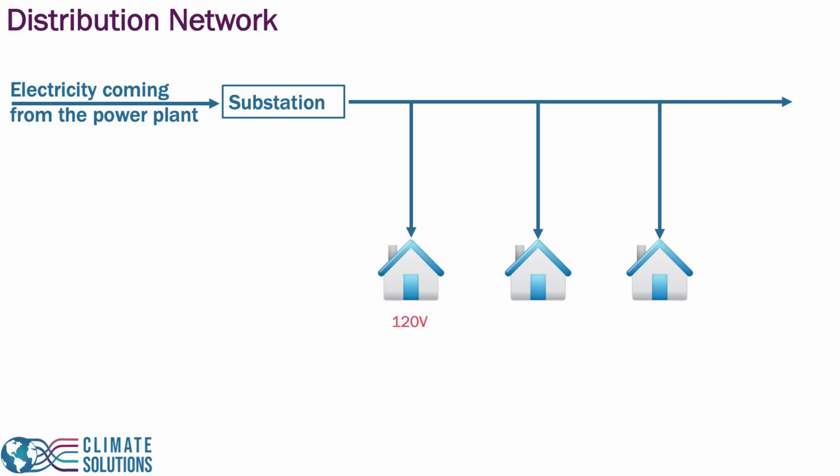And the reason I say almost magically is, remember, there is no storage in the system. And so what's happening is there's a dip in voltage, and the system is sensing that, and we'll talk about how, and then increasing the total amount of power flowing in the network to make up for the fact that you just turned on your vacuum cleaner. Now, of course, a vacuum cleaner is a trivial amount of power, but this has to be done at the city level or at the state level, right? We need to anticipate and respond to changes in demand and build a system that is robust to that.